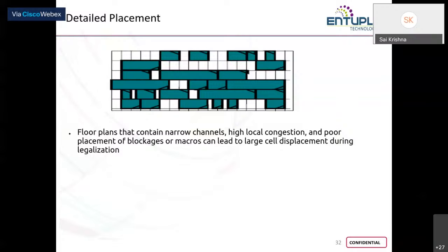That means it is placed correctly within its position, respecting its boundaries, and also proper spacing between two adjacent cells is given in such a way that if there are any pins on the opposite faces of two adjacent cells, there is enough space for those pins to be routed with metal layers. I hope I made my point clear.